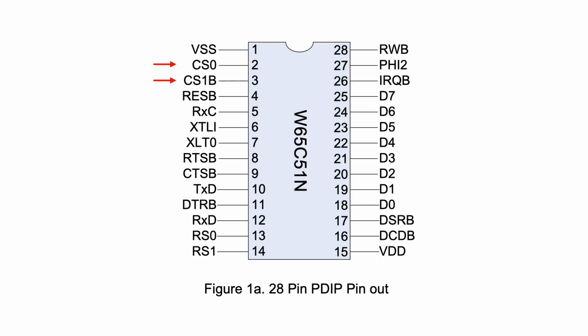Let's go back to the 6551 ACIA and its two chip select inputs, and what I said earlier about how we can get some additional address decoding flexibility if we're willing to fiddle with, or more specifically invert, some of the address lines on a per device basis. I already know that I want to have more than one serial port on the playground, and I already know that I'm going to need more than one 6521 PIA to control RAM and ROM banking. Now, I'd like to group devices with similar functions together and minimize the number of I/O device selects used by devices that are present on the main board if possible.